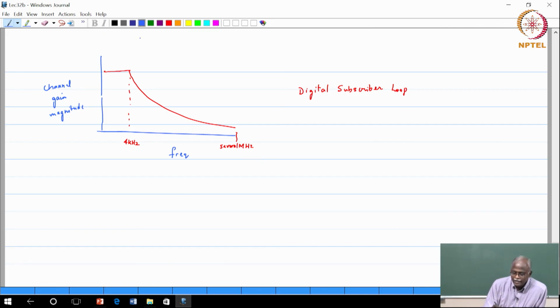So I say that, okay, leave this portion, I want to transmit something on this part. Okay, so if I transmit a signal that is like this, it is getting heavily distorted, and equalization becomes complex because I have to now design a very complex equalizer. Then these people said, hey, you know what, do not do this, transmit in small narrow bands. And then what do you do? Do water filling, do single tap equalization, get the signal out. So this is why they were interested in it.